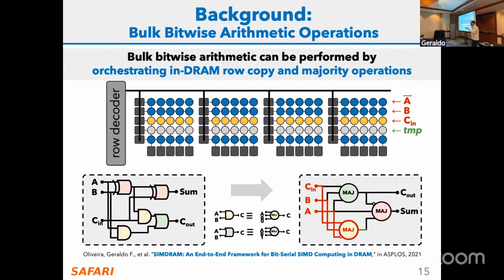We call them the N word line and the D word line. If you access the N word line, basically what you're getting is the output of the inverter from the sense amplifier. So you are actually physically negating and writing back to the cell. It's special in the sense that you need to have this rewiring, but the cell itself is still a DRAM cell, basically an access transistor and a storage capacitor. The storage capacitor is the same. We don't change it. We just have another access transistor that comes from the other end of the local sense amplifier.